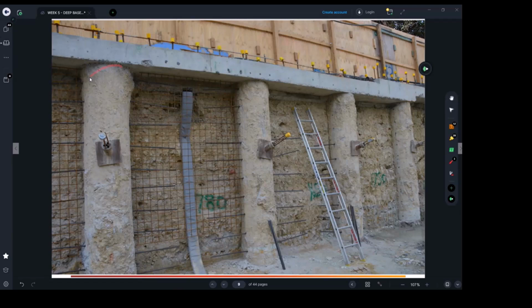Day one, we're gonna excavate for the holes. So no cut, no basement. We're gonna excavate for the holes, pour the concrete, and put the cage, right? If it was a CFA method, then we start excavating. Sorry, before that, we have to put the bars for the pile cap and pour the pile cap. When it gets hard and sets, we will then start excavating. It's up to the engineer. We can't excavate 3 meters in one go. If it was okay, but usually it is like halfway.